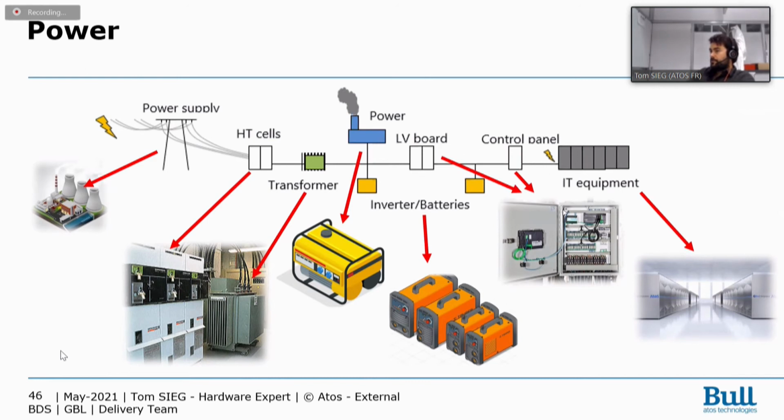LV board, control panel, it's an important part, but more for the security and for the monitoring. You will need to maybe monitor your power consumption, to maybe cut electricity remotely. If you want a remote control, you have to take care of what you put in your control panel.